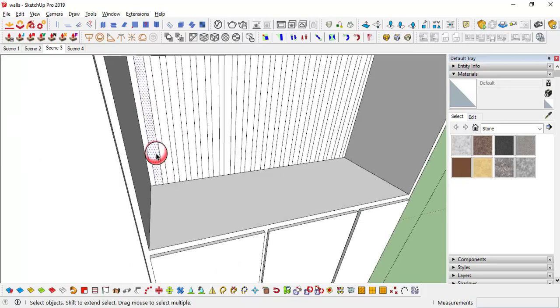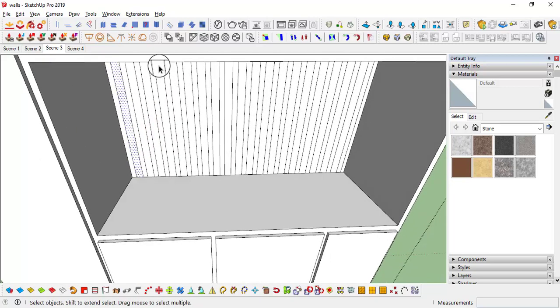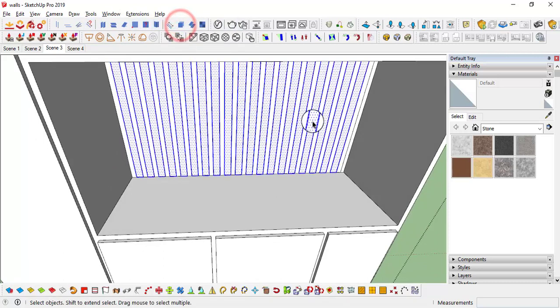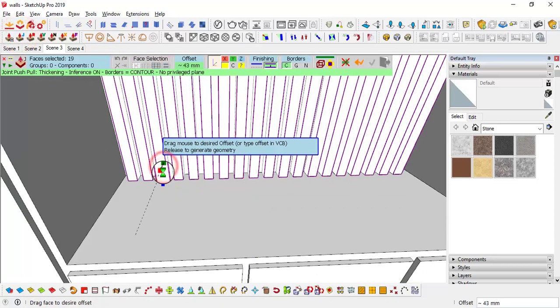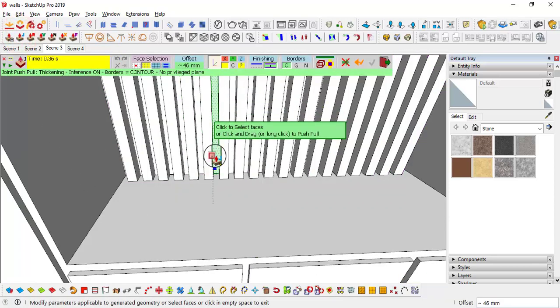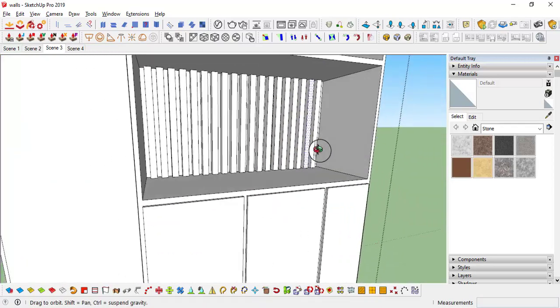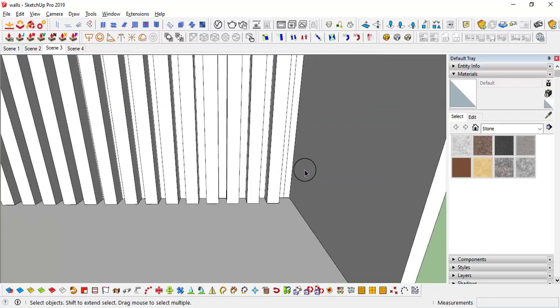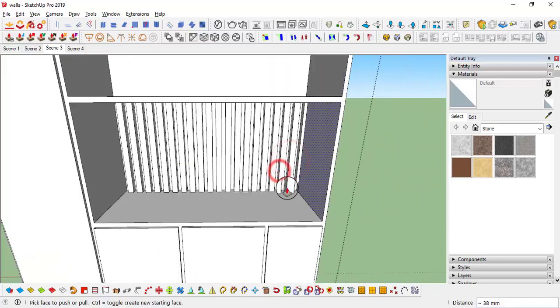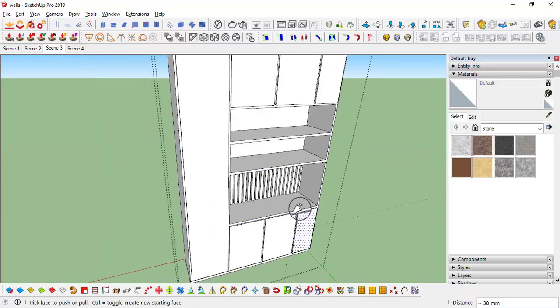Now select this one, okay, and use similar in the selection tools, similar same area. See, all that will be selected. Join, push pull. How much? This is like 1.5 inches. See, there go our rafters, and push pull up to here. See, this is desk only.